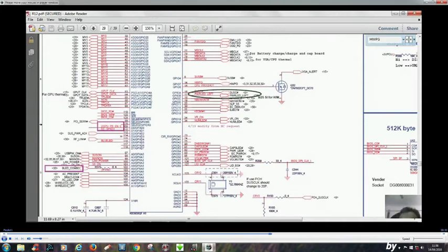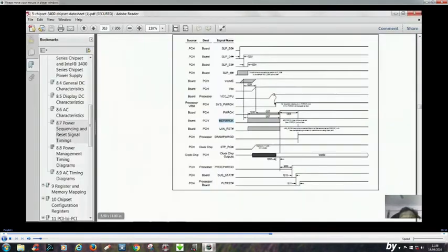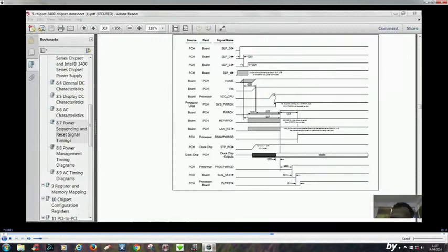After the IO controller receives the hardware power good, it will generate the EC power OK signal, and this EC power OK signal is fed to the ME power OK, that is management engine power OK. So this is the relationship of how the IO controller works in connection with the PCH, right? Okay, so we have seen signals up to ME power OK.